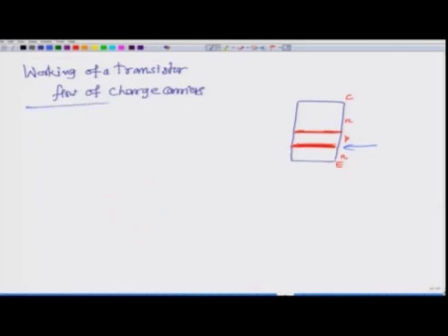Okay. So, let us connect it. First, that input side. On the input side you have this base, and then you have some resistance here, and then you have a battery, and I have to connect positive here and negative here, and then it goes to this one. So, this junction is forward biased, and remember this emitter is heavily doped and it is forward biased.